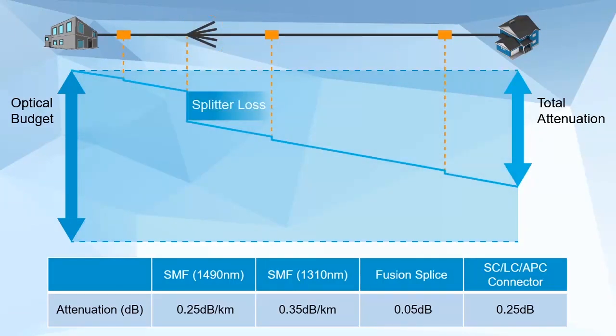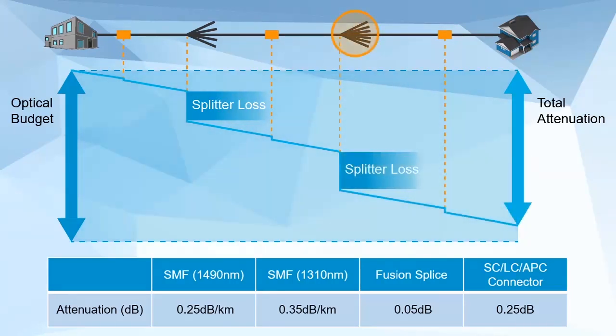This example shown has only one splitter and would be where the PON is serving a group of subscribers in a fairly remote area. Here there are two splitters in the link, so the loss just from the splitters will be double what we saw in the previous link. There are still the same number of other connections, so the attenuation is calculated per link from the central office to the subscriber's ONU, and each will be different due to the actual length of the fiber in the channel.